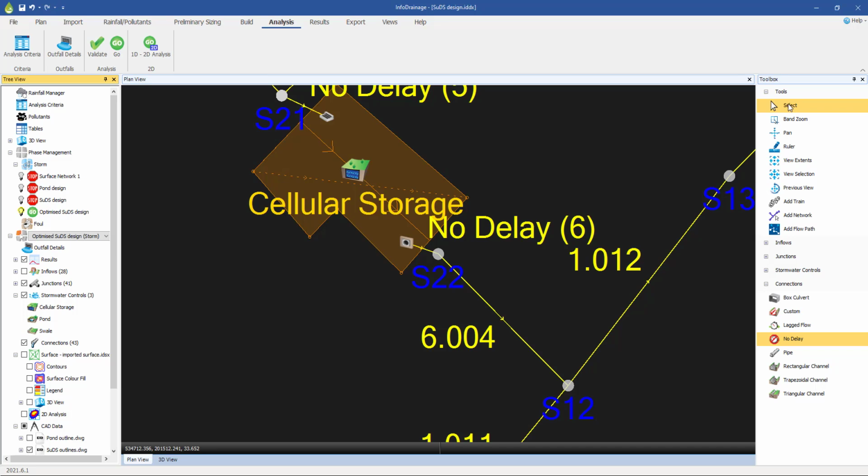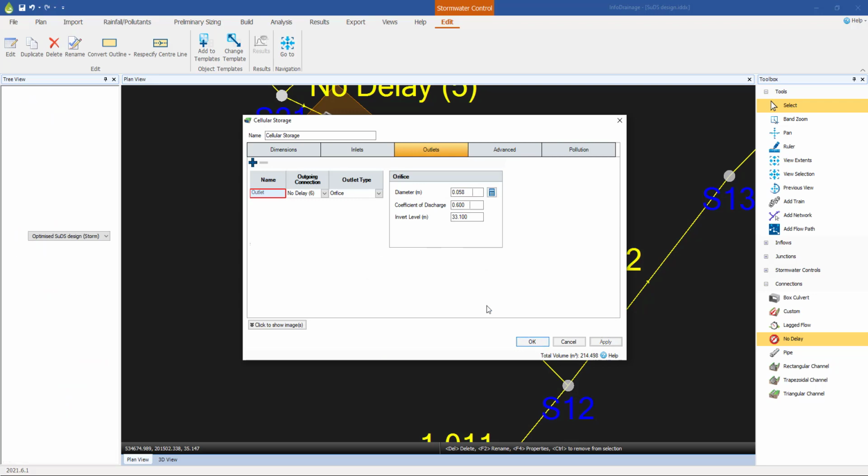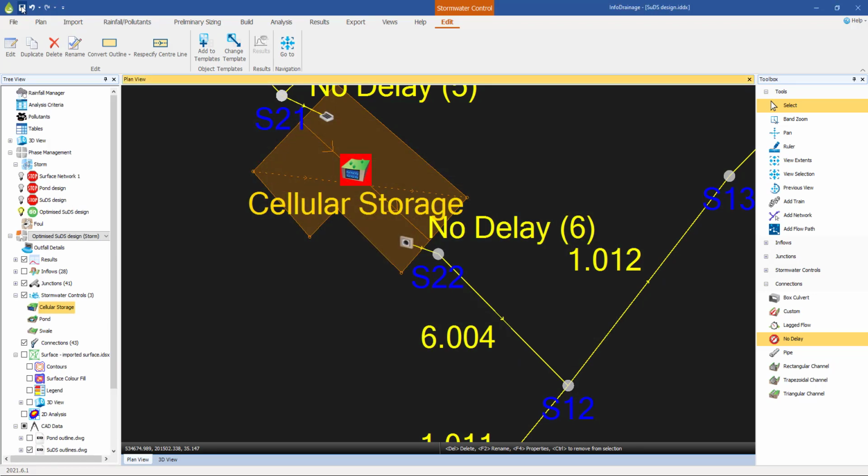So I have to sort of give away, show you behind the curtain a little bit. I would probably have guessed 8 litres a second and run it. That was still a little bit over designed, so I then went to 7 litres a second. So let's jump straight to 7 litres a second. So rather than design flow being 9, we're going to go for 7. OK. Save the model.